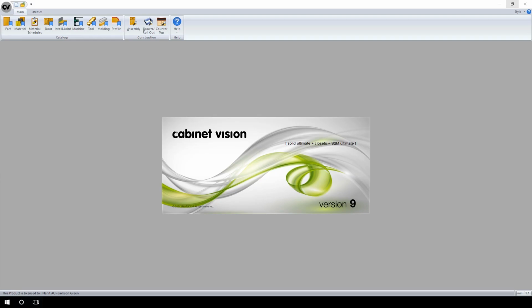Hello and welcome to the Planit Cutting Edge Solutions tutorial on Object Tree. This video will take us through how to utilize Object Tree to apply equations to parts, which allows us to build parametric cabinets. A parametric assembly or cabinet is able to be sized with all the internal parts and components staying in the correct desired position.